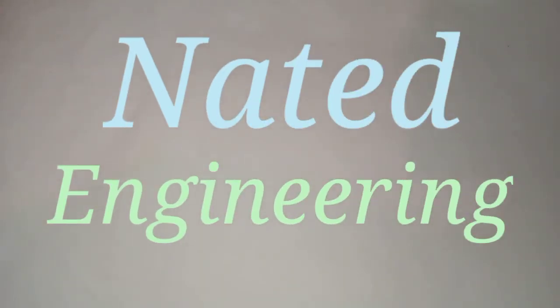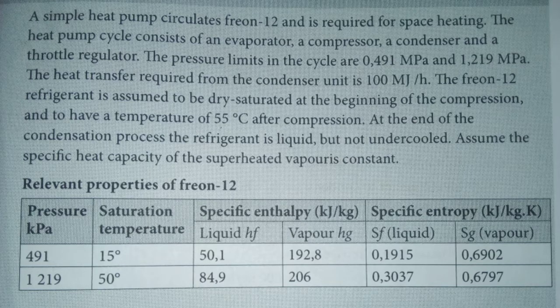We are doing an exercise on refrigeration power machines, and it reads as follows. A simple heat pump circulates Freon 12 and is required for space heating. The heat pump cycle consists of an evaporator, a compressor, a condenser, and a throttle regulator. The pressure limits in the cycle are 0.491 megapascal and 1.219 megapascal. The heat transfer required from the condenser unit is 100 megajoules per hour.